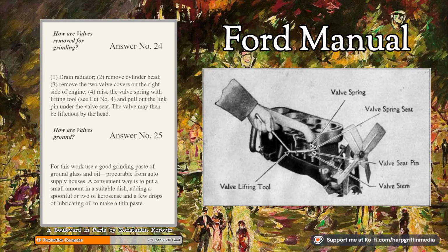4. Raise the valve spring with lifting tool. See cut number 4. And pull out the link pin under the valve seat. The valve may then be lifted out by the head.